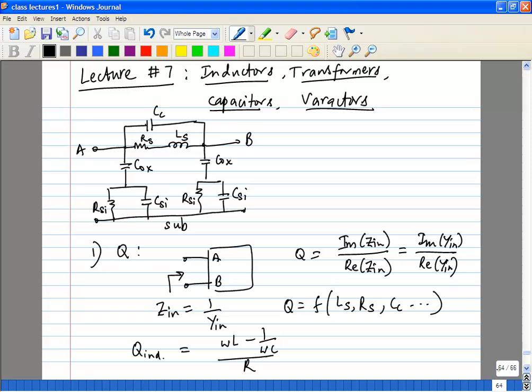So you want to create your inductor, you want to use M6 to M2 and ground M1. You could do that, but remember, if you do that, the CC will first of all increase because you have parallel combinations of M6 inductor, M5 inductor, and so on. And of course your Cox will also increase, because at the end of the day, the capacitance to substrate will go through M1 to your substrate. So it will still be high.